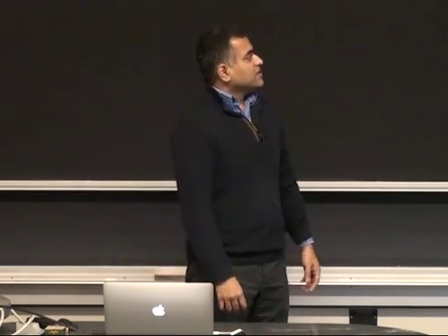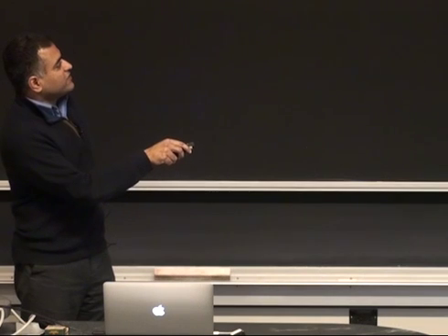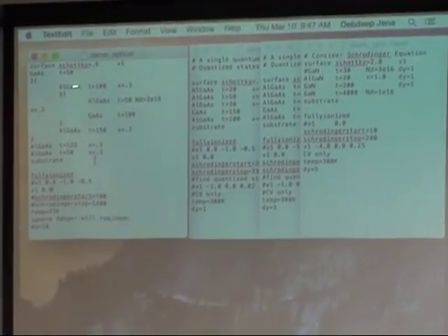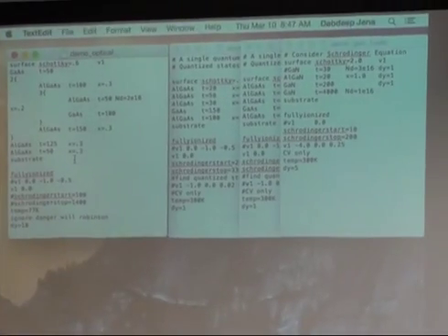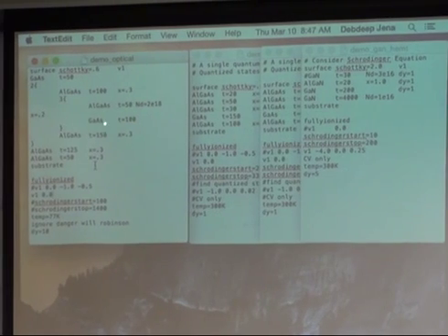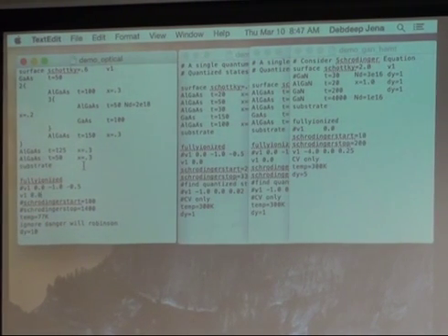It's an optical design which has multiple layers: 50 angstrom, 5 nanometer, of gallium arsenide on the top. And then, if you look into details, 100 angstrom of aluminum gallium arsenide with 30% aluminum, then aluminum gallium arsenide that's doped, gallium arsenide, and this thing repeats 3 times, and so on. So this was the detail.